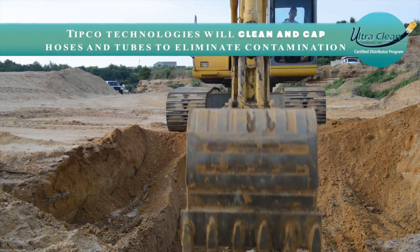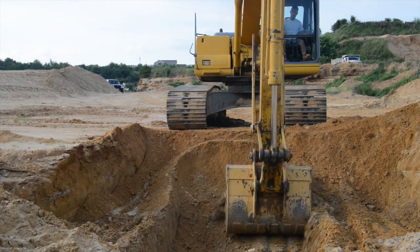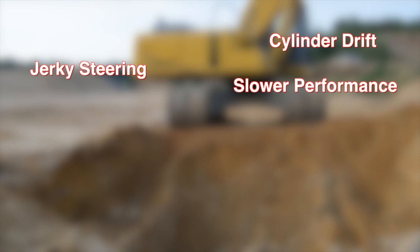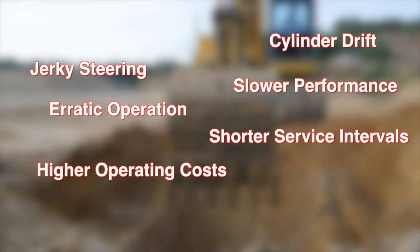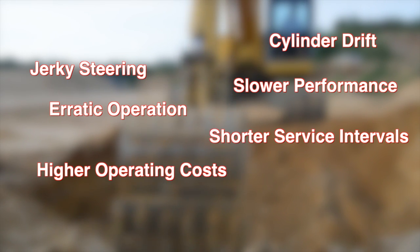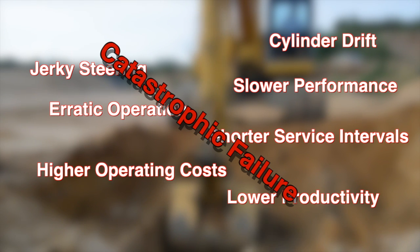Equipment owners and operators also see other common effects of hydraulic system contamination, including cylinder drift, jerky steering, slower performance, erratic operation, shorter service intervals, higher operating costs, lower productivity, and possible catastrophic failure.